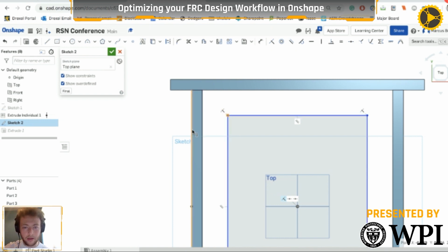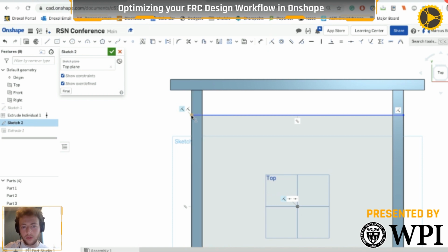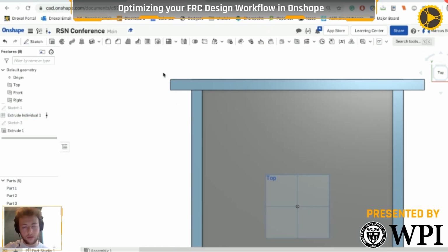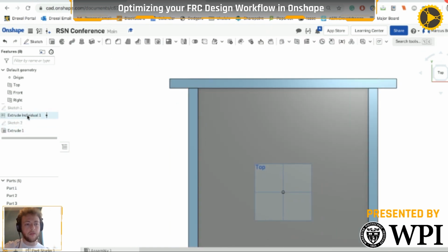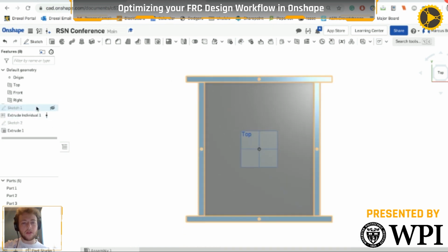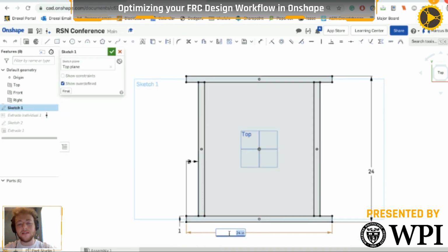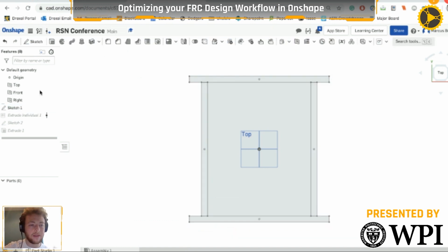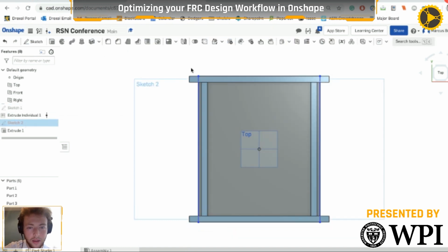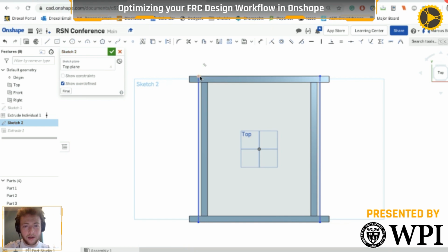I can set these two to be coincident. That's the coincident constraint right there, though I use the hotkey, and that point and that line to be coincident. What's nice about that, and of course this same logic will transfer over to other CAD platforms, is they're set up in such a way that if I go back in and realize that this needs to be 23 inches, I can then do that. And obviously, because that's dependent, just kidding, it broke because I set it up poorly.